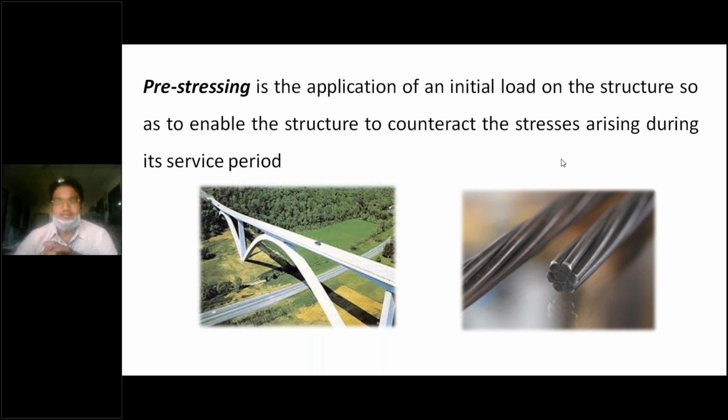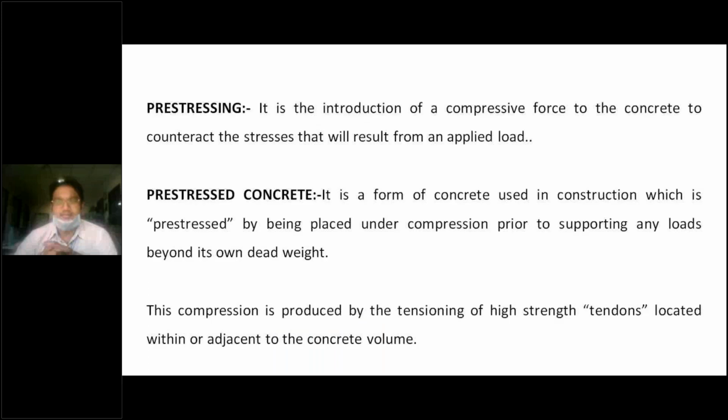Next, coming to the difference between prestressing and prestressed concrete. Just now we went through that prestressing is an introduction of a compressive force. Here, when we apply tensile stresses to the strands, you are applying compression forces to the concrete. When you come to college, I will definitely show you a live example of how prestressing can be applied, where the steel rods in a concrete member are subjected to tension and the concrete is subjected to compression.